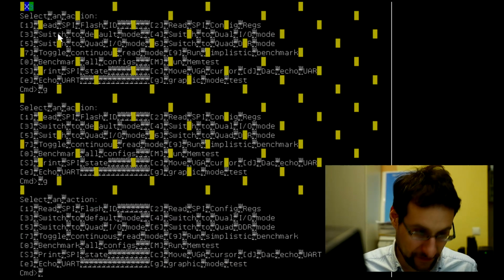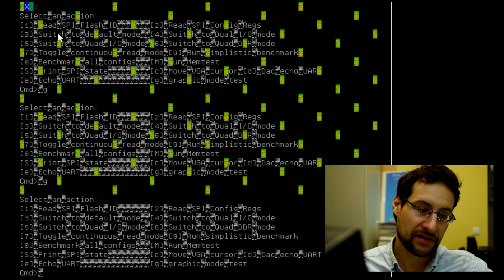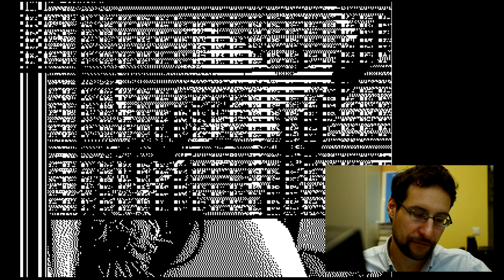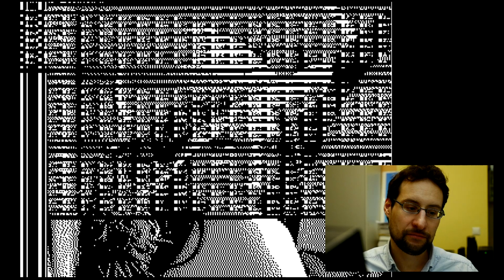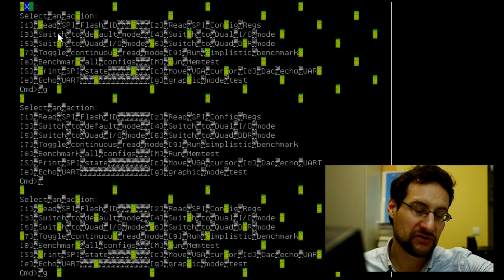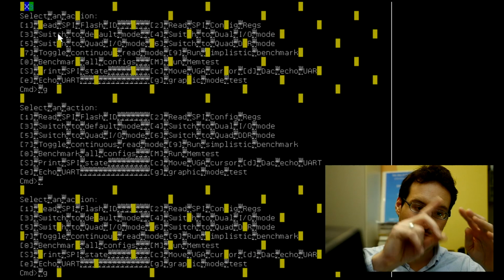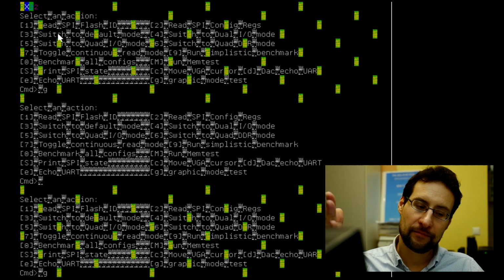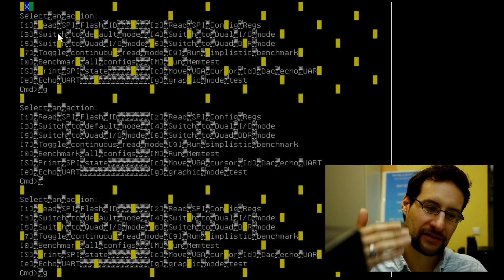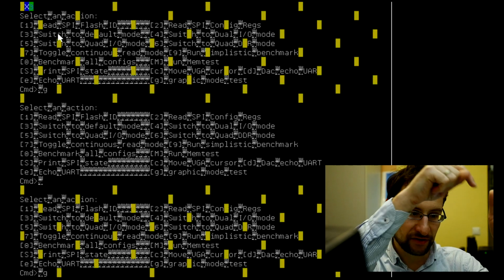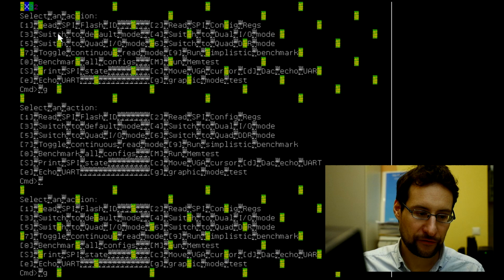This pattern there is, by the way, something I filled for testing purposes to debug this. I fill the very first 16-bit of graphic here with this test stripe pattern. So there you see the locations. They are 320 bytes divided by 16 or so, multiplied by 2, because character set and text attribute are apart. This is just the distance of the frame buffer scan lines there.